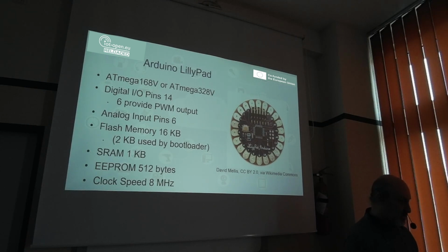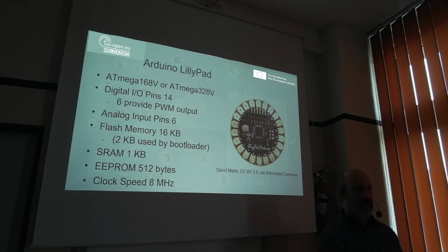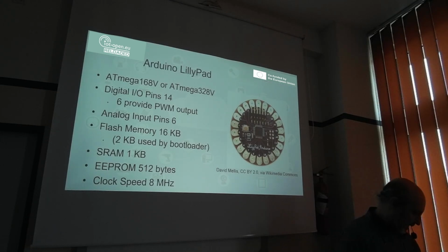It is based on a similar microcontroller as the previous one, but it doesn't have a USB connection. So it doesn't allow being programmed directly, it needs an external programmer. But in such a situation it consumes less power, so it's better for wearable devices. And it has a reduced clock speed to preserve power during program execution.